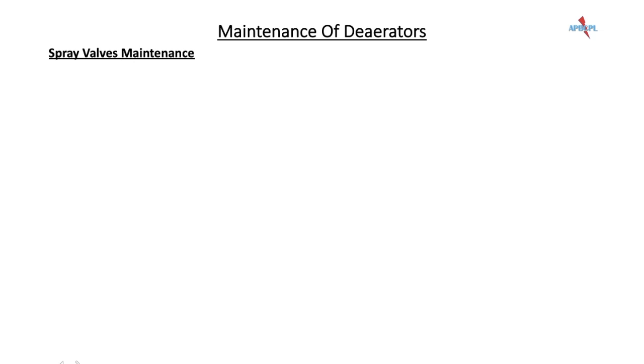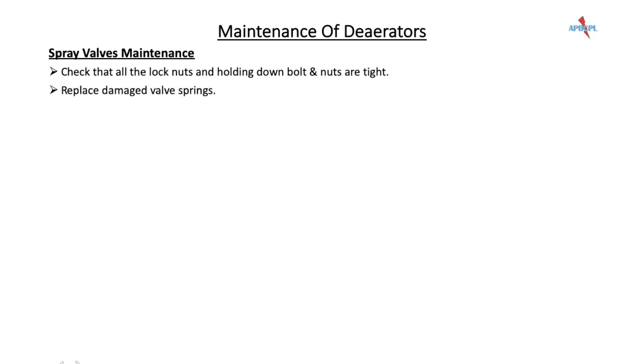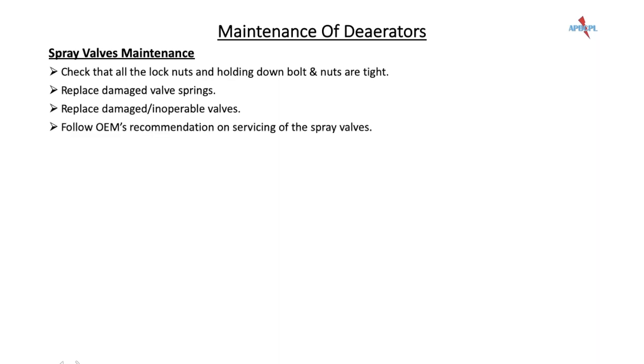Spray valves maintenance. Check that all the lock nuts and holding down bolt and nuts are tight. Replace damaged valve springs. Replace damaged or inoperable valves. Follow OEM's recommendation on servicing of the spray valves.